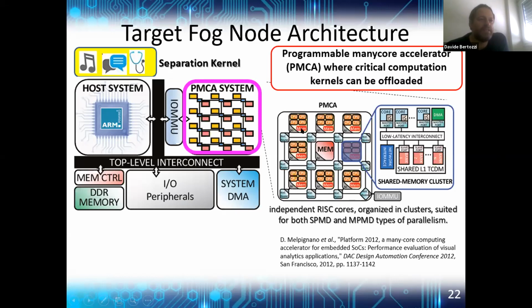It's a two-dimensional grid of computation clusters, and cluster-based architectures are currently mainstream in the high-end embedded computing domain. Think, for instance, about the Kalray MPPA architectures, the Platform 2012 architecture, and so on. Moreover, here you can see that for each computing cluster, you have a distributed bank of L2 memory. So the memory organization here is distributed shared memory.